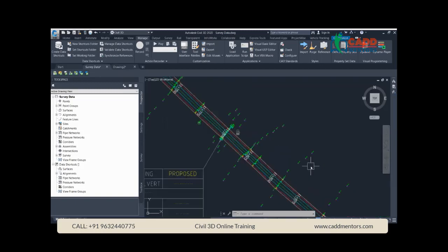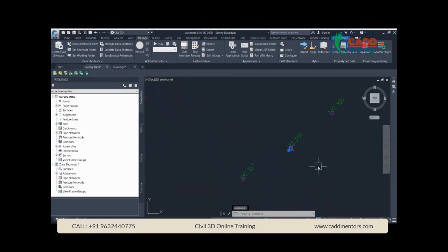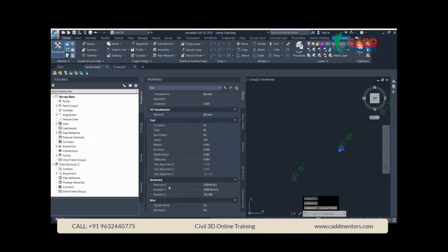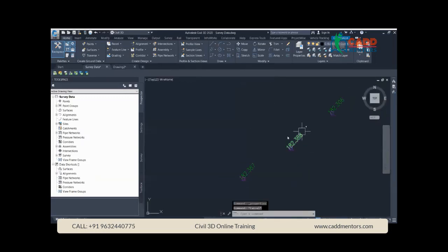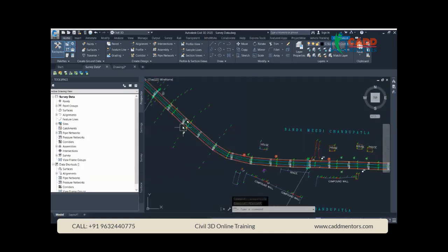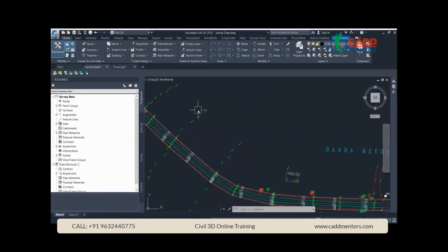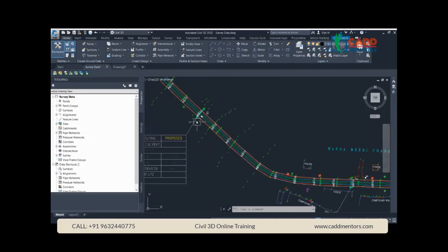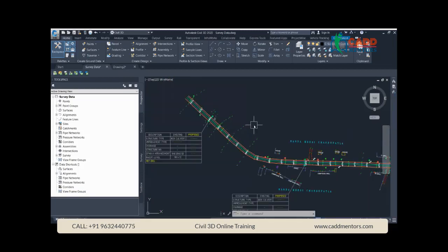So when I'm selecting this point here and I see its properties, you can see it. This is what I meant by x, y, z: the positions, northing, easting, and the elevation of that particular point on the ground. The surveyor will take it and record it in the system. Sometimes we get the data like this, and sometimes we get only the point data, where you only have the elevation and you do not have these lines. Sometimes we even get that as well.